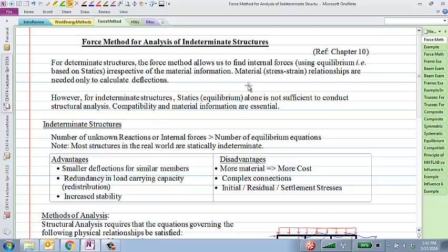But say one of the springs is extremely soft and the other spring is much stiffer, then where would the load go? To the stiffer spring, right? Even though the displacement for both of them would be exactly the same, the softer spring does not carry any load because its force for that displacement is very small. The stiffer spring, even with a small displacement, carries most of the load P. So that's an example of a system that is indeterminate: two simple springs hanging from the ceiling. You cannot use equilibrium alone to find the forces in the springs. We need the material properties of the two springs.